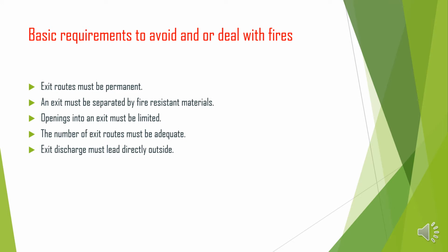Exit discharge must lead directly outside the building. Don't give me an exit that leads to the inside of the facility, where I will still be in danger. The exit must discharge me outside the hospital into an open area to avoid the smoke and the fire. Exit doors must be unlockable from inside. We just push from inside and it opens directly. We cannot put a lock or a key or something like this, because at the time of the fire we don't have to search for the key. We just push it and go outside.